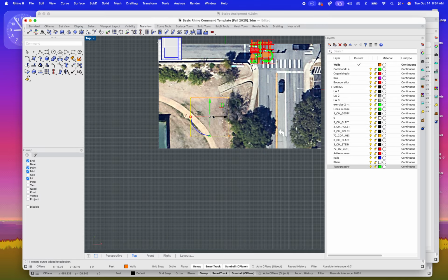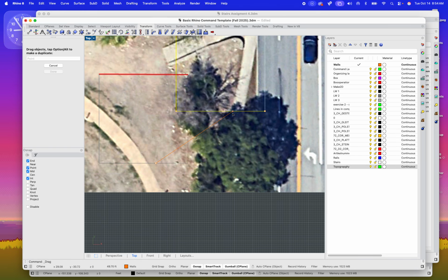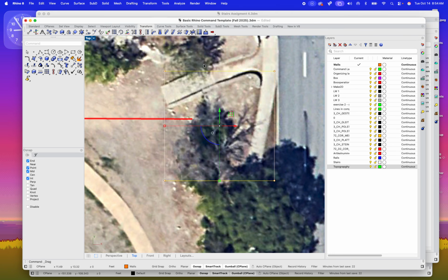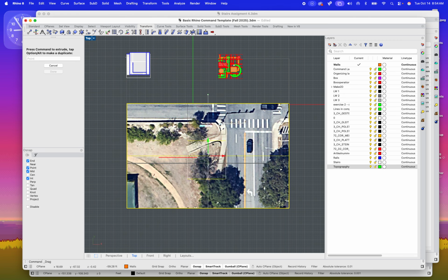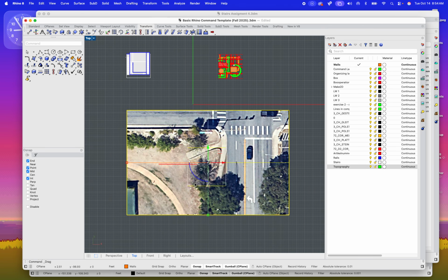And to be fair, now I can move this rectangle around and I have 48 feet everywhere, right? Obviously. So in my case, I'm going to choose maybe this part of my piece, maybe a bit of the stair in there. That's looking pretty good. And to be fair, I do need the other topography piece. It'll be a lot easier to line up that drawing, especially if I have some more stuff in it. So let's type in picture again.